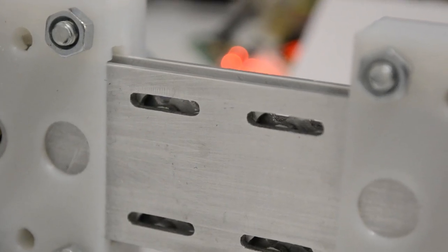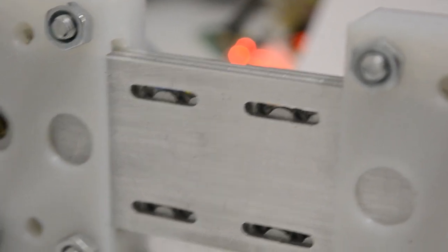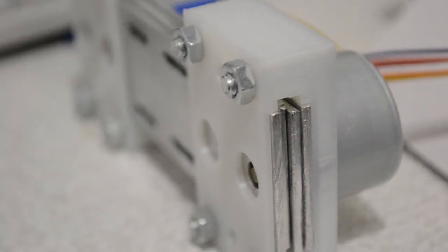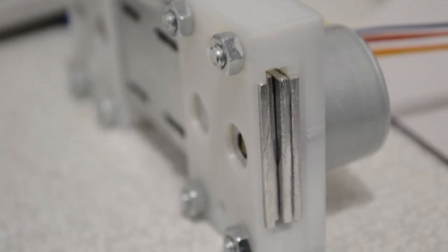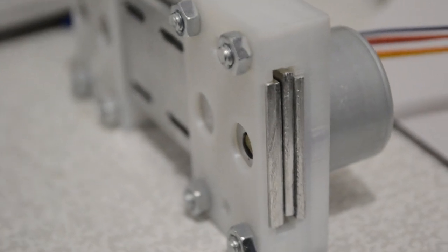As you can see here, the actuator is made out of 4 plates, 2 of which are guiding plates for alignment and 2 are pushing sliders. In this device, sliders travel in circles with a radius of 1 mm relative to the alignment plate. Sliders are 180 degrees out of phase.